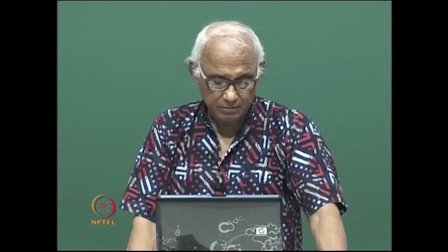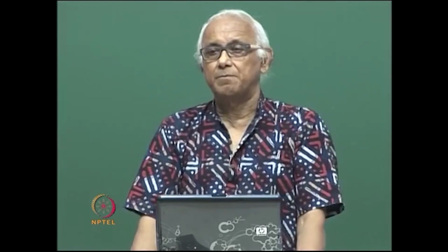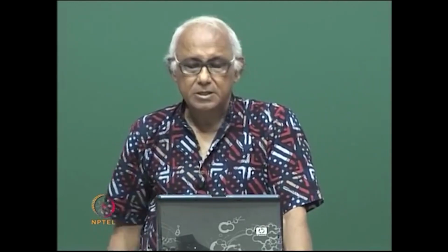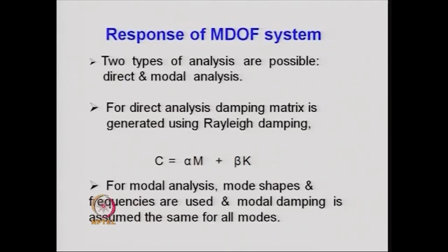In fact, any two frequencies can be taken, and which two frequencies will describe the damping matrix best is a matter of debate and research. But generally, for the solution of the problems, we satisfy ourselves by considering only the first two frequencies. For modal analysis, we will require mode shapes and frequencies that we will discuss later.